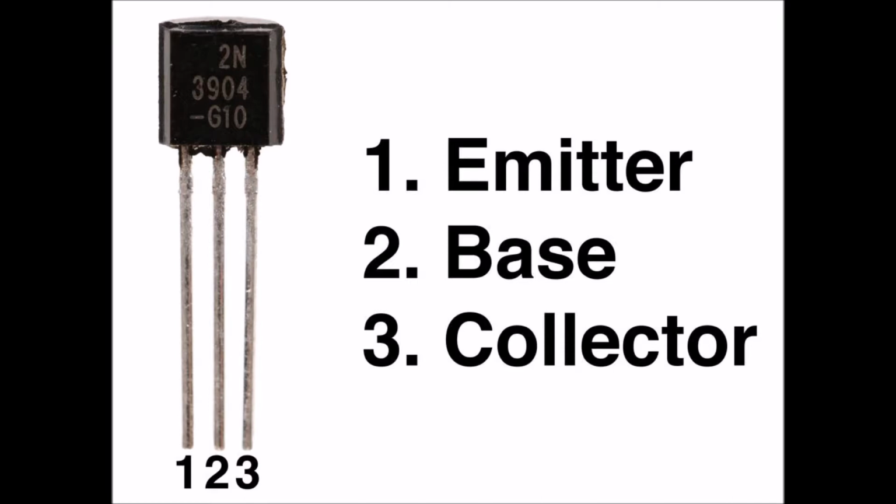The beta for any transistor can exceed 1 and often does, greatly. So this expression for current gain lives up to its name. However, under some conditions, we might observe a beta of less than 1. This condition can occur if we improperly bias a transistor, if we choose the wrong type of transistor for a particular application, or if we attempt to operate the transistor at a signal frequency that's far higher than the maximum frequency for which it is designed.